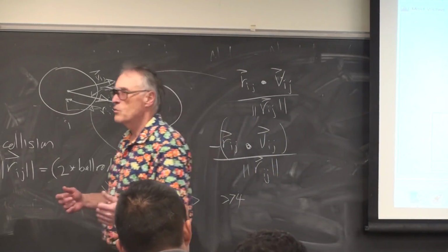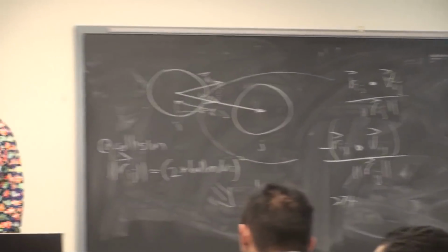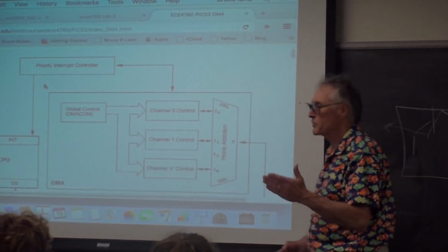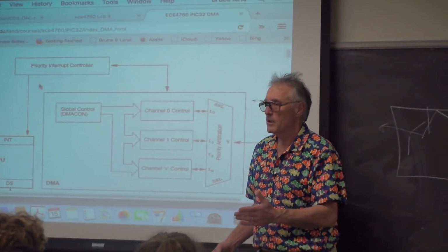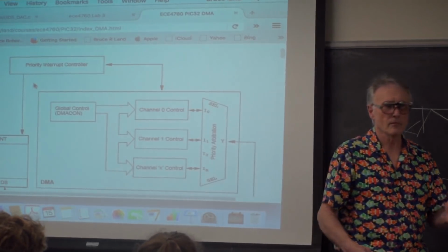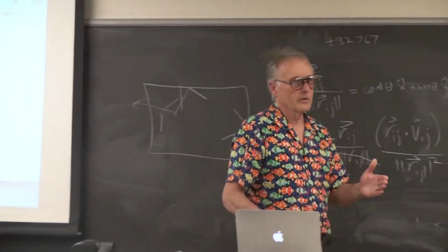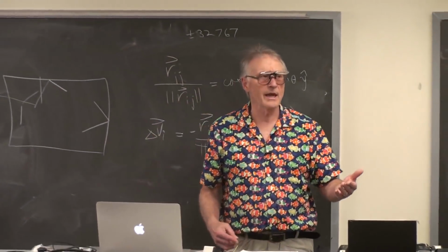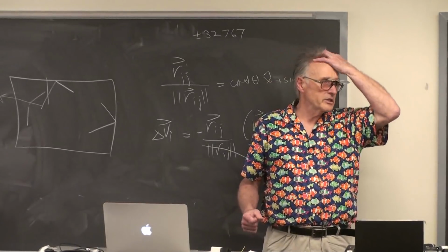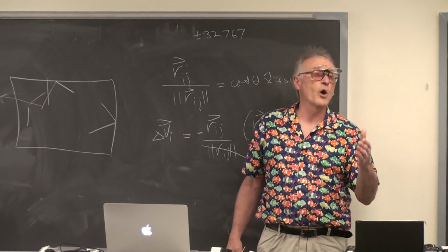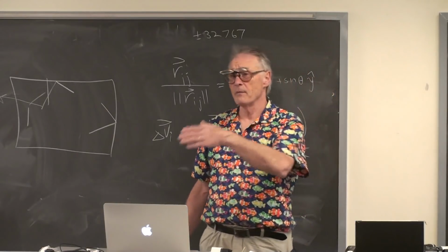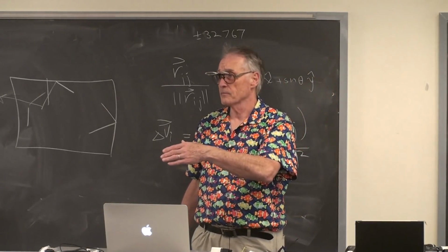So you have this weird situation then of a completely, truly parallel processor doing something for you, if you can only aim it in the right direction. I don't think you're going to do this in this lab, but one of the things I've done with it is to grab data from the analog to digital converter at a megahertz. In fact, it's the only way to get data out of the A to D converter at a megahertz, and barf it into main memory, into data memory.